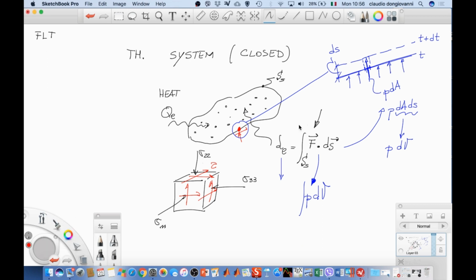In this idea, force and displacement are in the same direction, okay? So is the work positive or negative? Positive, okay. But if I have a positive work, in my previous analysis, I have a reduction in volume. Therefore, will dV be positive or negative? Negative. So, the first relationship says positive.